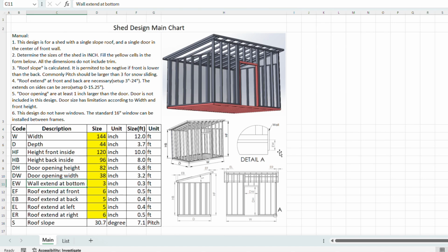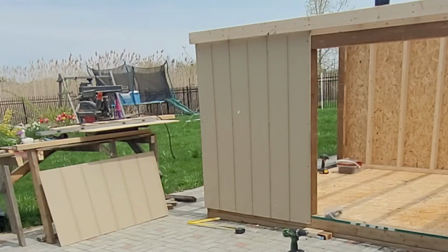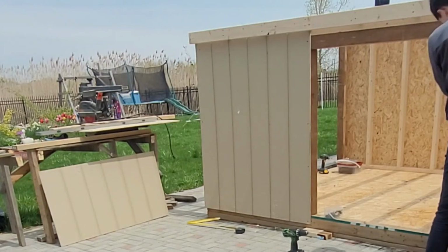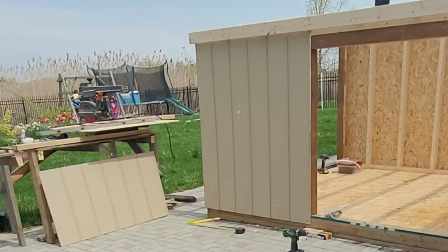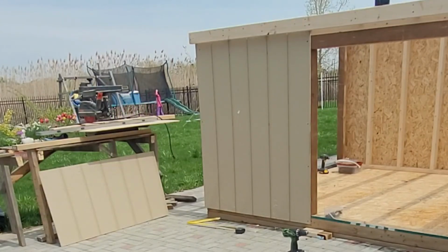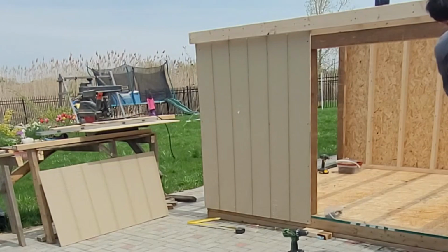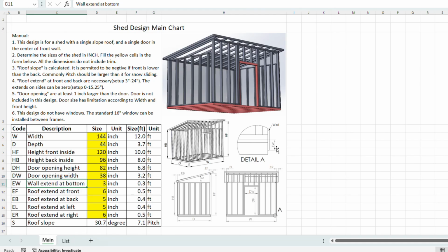When you install a wall, it goes over the wall frame to cover the gap between the wall frame and base frame. But you need to leave a gap between the wall and your foundation, so that water trapped on the foundation will not reach the wall. So make sure to set it to a proper height.